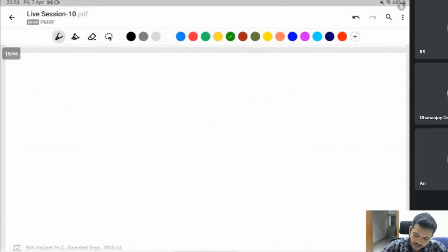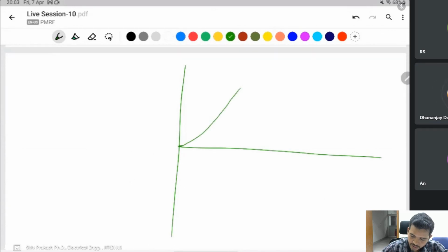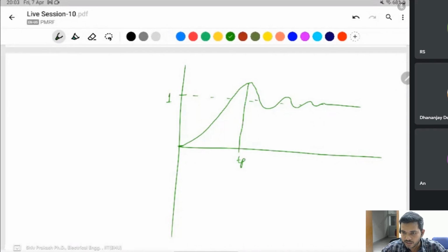You know about that? If you have a step control response, given a step input of 1, the time to reach 90% of the steady state value is the settling time. It can be 90, 95, 98%, depending on the definition. If it is 3 tau, it means 95%. If you have 5 tau, it means 98%.